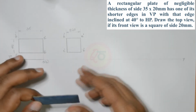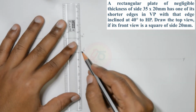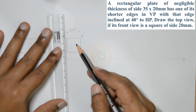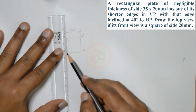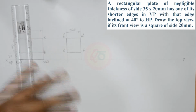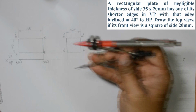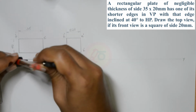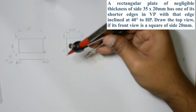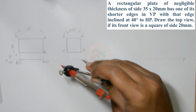So, take the projections from the resting edge, which is A dash, B dash, up to the XY line. Okay. And from C dash, D dash, extend it beyond the XY line sufficiently downwards. Next, measure AB to DC in the first position top view from the projections from A dash B dash on the XY line.